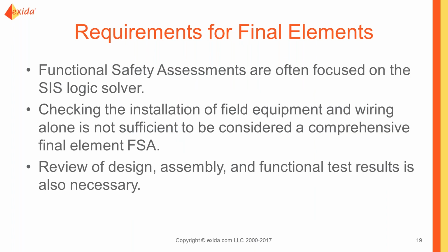So for final elements, it's important to pause and kind of consider them in context. So often there are changes and things are going on with the logic solver, so sometimes it can take the majority of the focus, and not that that's inappropriate, but I've seen it happen where the focus has been on the logic solver, and because it's considered complex and changing, and sometimes not enough focus on the final elements. So we want to be careful about that. And essentially just checking installation of field equipment and wiring alone isn't really sufficient enough to be considered a comprehensive final element functional safety assessment. So a review of the design, the assembly, the functional test results is also necessary to have a good holistic view of that final element and confirm that it is ready to do its job.